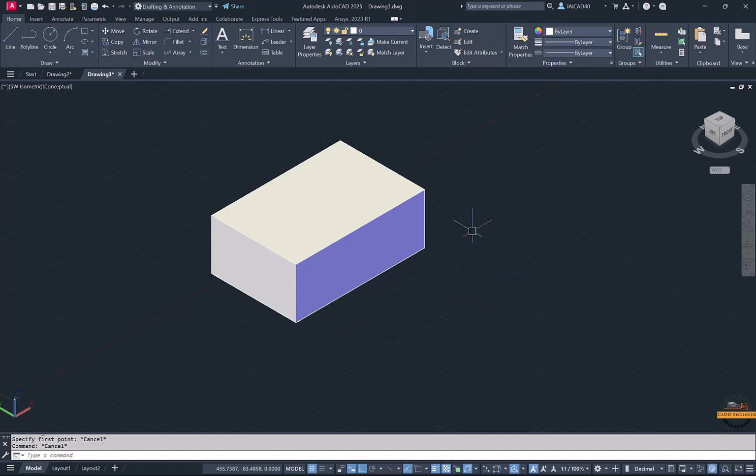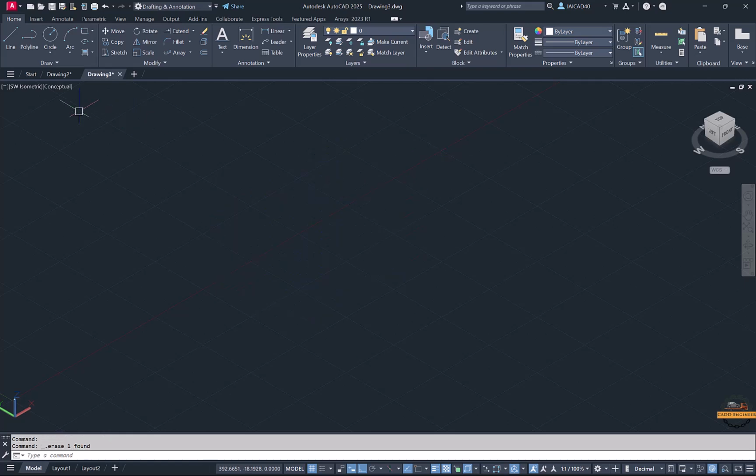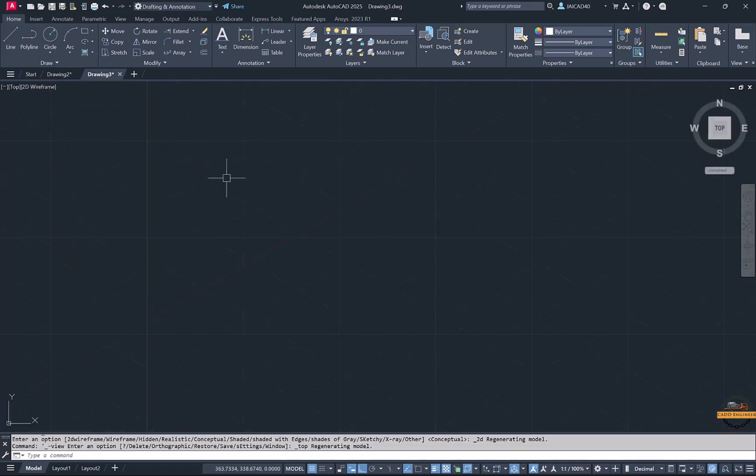Next is F5. F5 is again used in 3D, when we work in an isometric diagram, to change the view. Let me turn on the isometric draft and show you. Press the F5 button. You can see the direction of the grids and the cursor change. When we're working on isometric diagrams, we can press F5 to change that. What is F6? Let me go back to normal. F6 is dynamic UCS, which is again used when you work in 3D. In that case, you can manage the UCS.